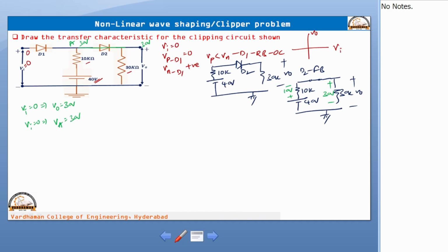That means here one thing you can observe: VA is 30, meaning the inside voltage for diode D1 is 30. So, to make this particular diode turn on, you have to apply a P side voltage greater than 30. This is the critical part of this problem. So, listen carefully. We made VA 0, we got output 30 and VA is also 30. But VA is inside of diode D1, this is D1, here you have 30.